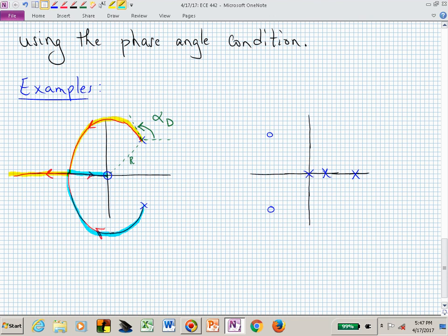And this picture is telling us what? Let's not lose track of what this root locus is really doing. This is showing the possible closed loop pole pattern, or the possible values for our closed loop poles for this combination of poles and zeros in our transfer function consisting of the plant and the controller. So for this combination of pole and zero, we can find a particular location by adjusting the gain k to a certain value.